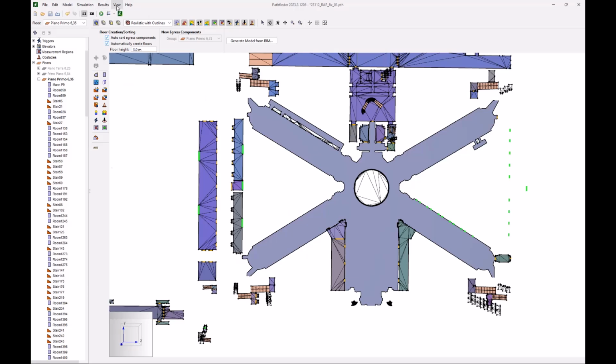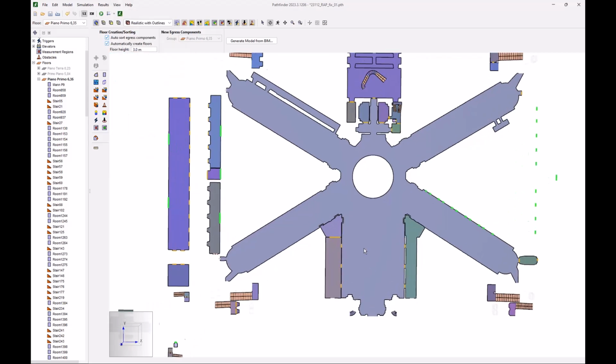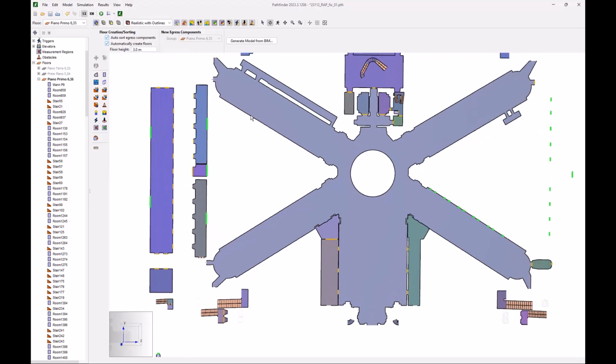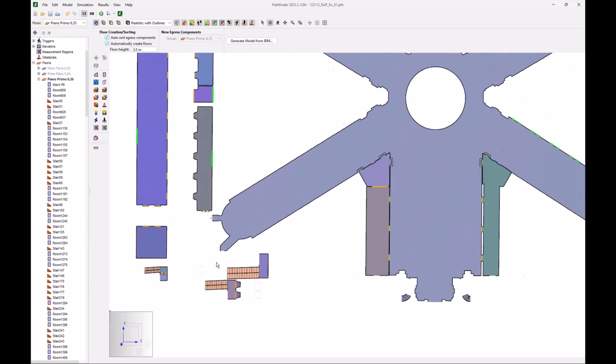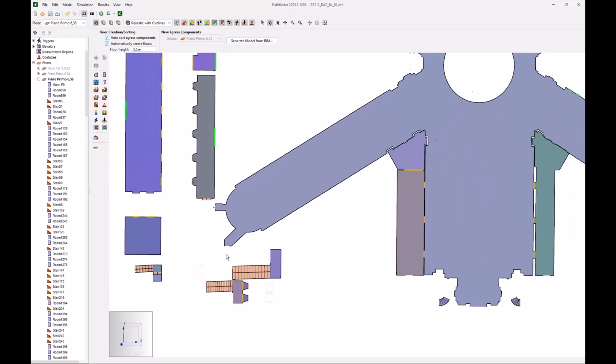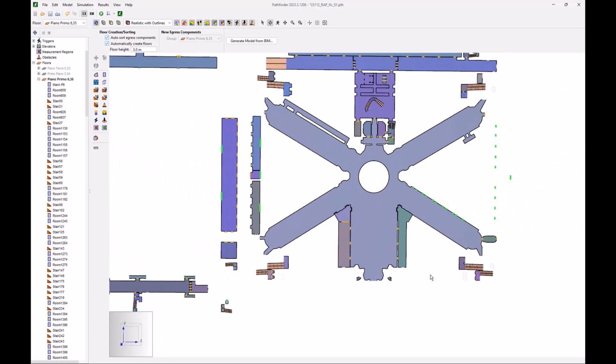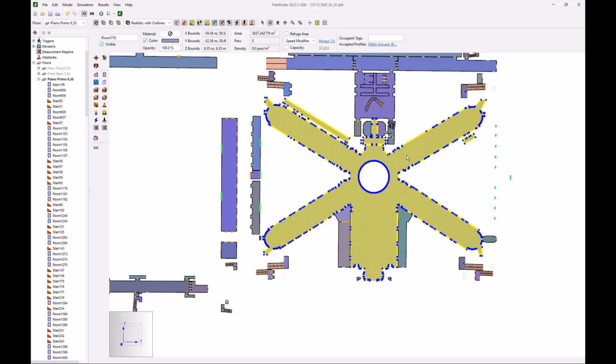So the first thing we'll do is turn off the triangulation display. That speeds up the model. If you explore the model, you see that there's no obvious reason that we can easily see that caused the problem with triangulation. It's not uncommon for this to happen when you have imported geometry. There can be gaps or something that just doesn't work right.